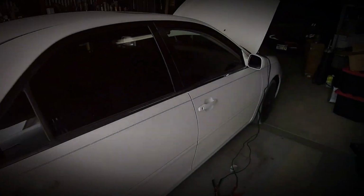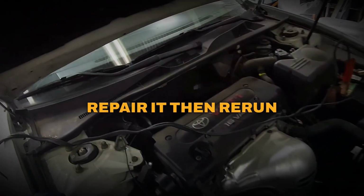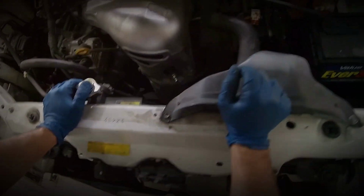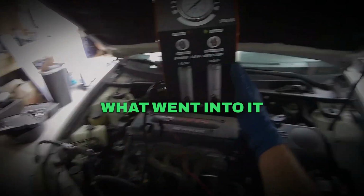If a leak is confirmed, repair it first. Then allow the vehicle to rerun the catalyst monitor under the required conditions. If the exhaust is sealed and P0420 returns, the next question becomes more important. What has the engine been sending into the converter?